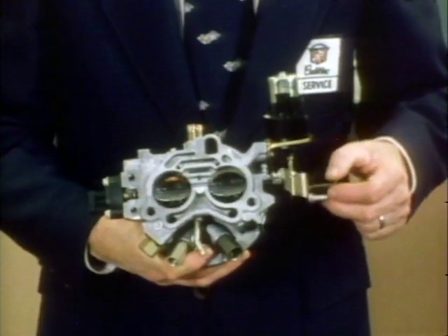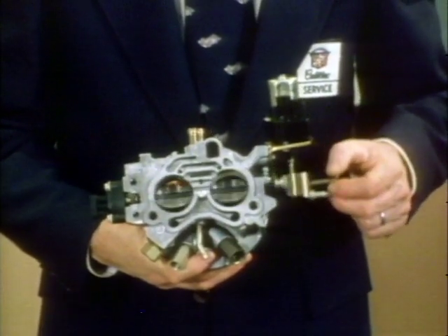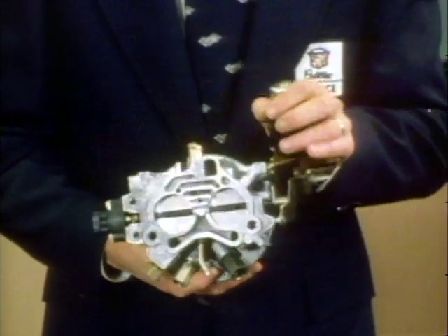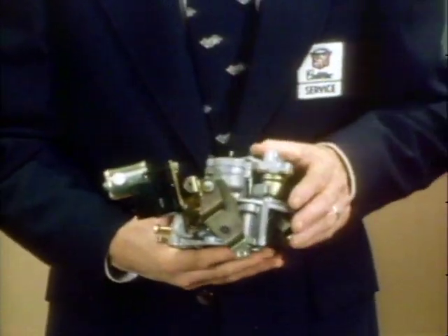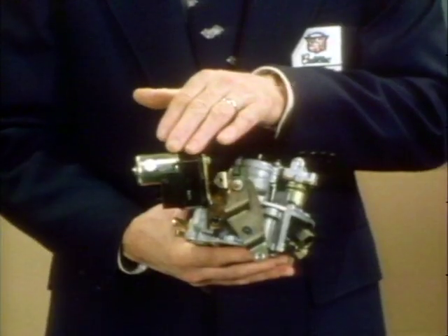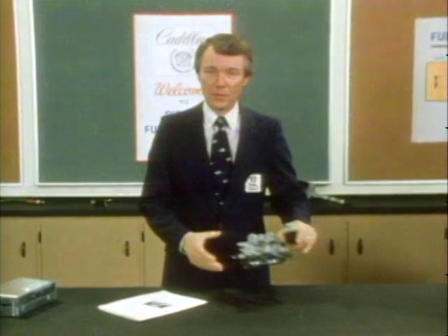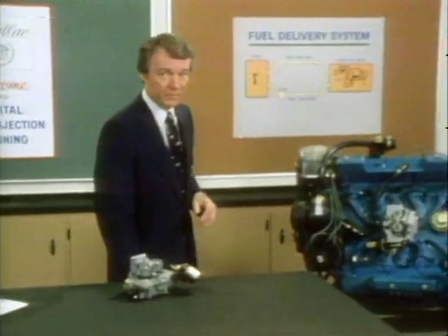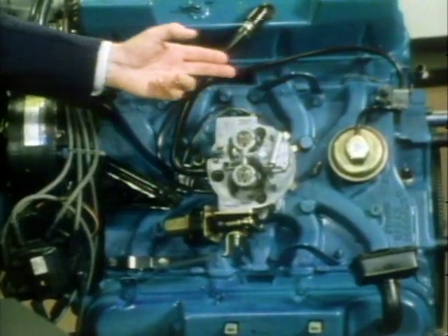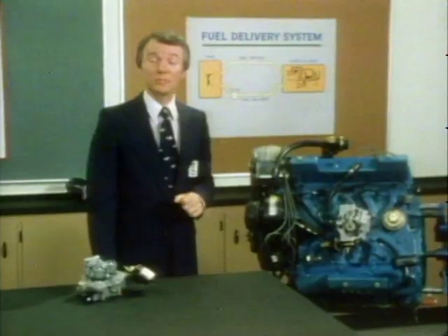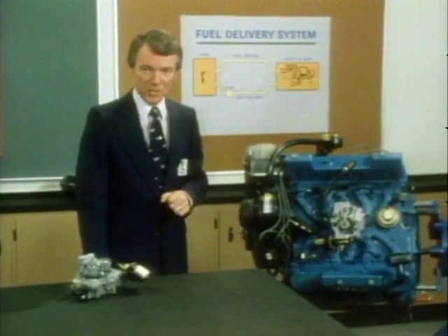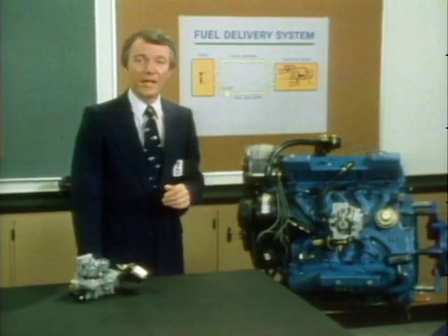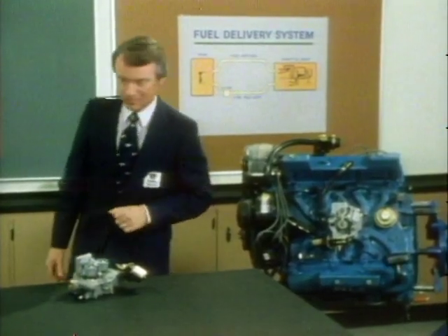The amount of opening by the throttle blades is a factor in determining the engine speed. Engine idle speed is controlled by the second component of the air induction system, the idle speed control actuator. The third component is the intake manifold, by which air is distributed to each cylinder. This manifold is an aluminum single-plane design, engineered especially for DFI engines with modulated displacement. That covers the DFI fuel delivery and air induction system components.